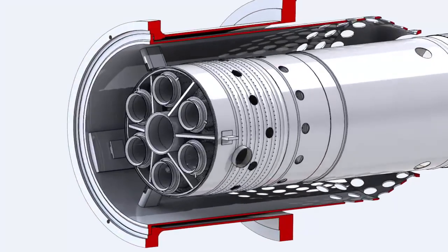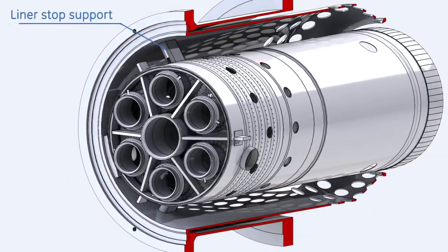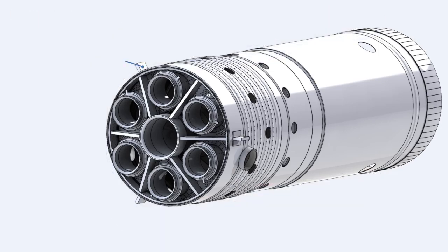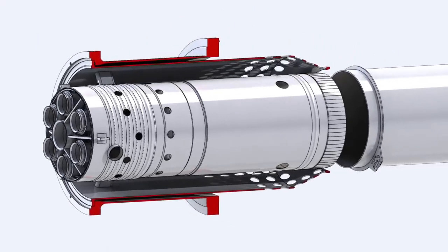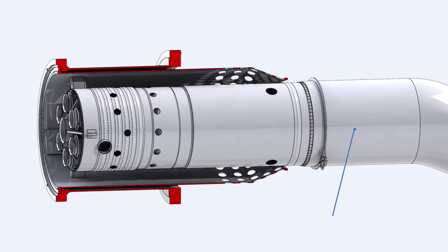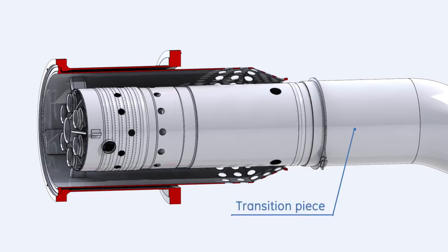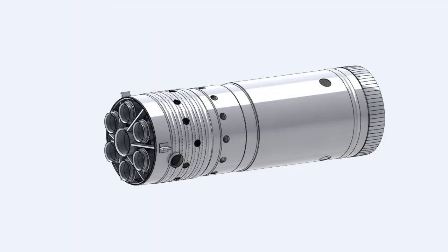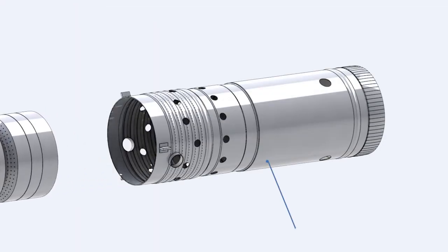The liner is mounted on the flow sleeve at the forward side by 3 liner stops, and supported at the aft by inserting the liner inside the transition piece. This configuration allows thermal expansion of the liner. Spring seals located at the aft end of the liner prevent the compressor discharge air from leaking into the hot gas path. The liner consists of the liner body,